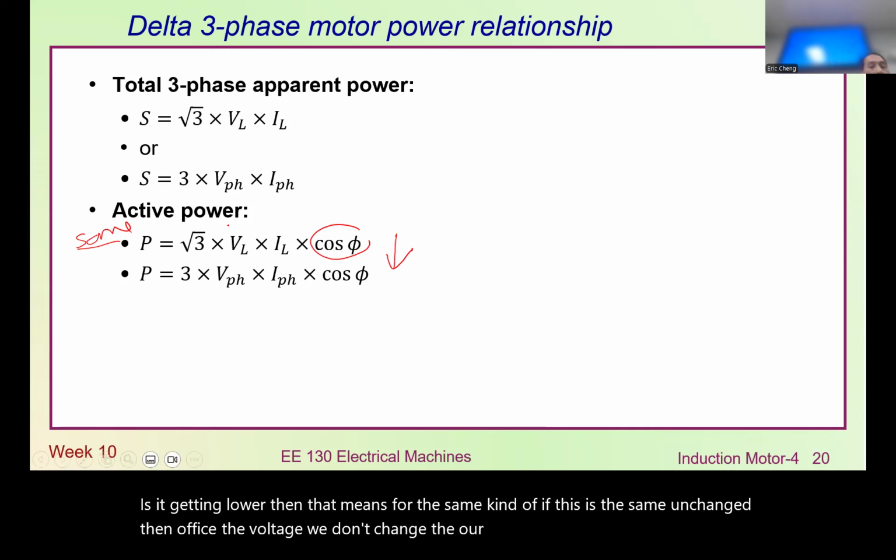So for the no-load test, that means the I2 here is not connected to anything, similar to a transformer without any load. Why is that? Because the motor torque is actually proportional to the motor current anyway. So when we do not connect anything to the shaft, there won't be any torque, or the torque will be negligible, really small. There may be some kind of windage loss, but we just ignore it for the moment. So in this case, we assume I2 will be 0.